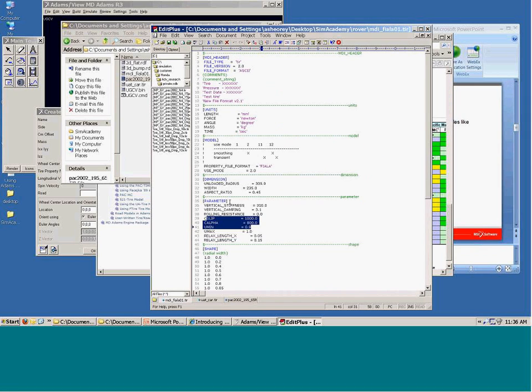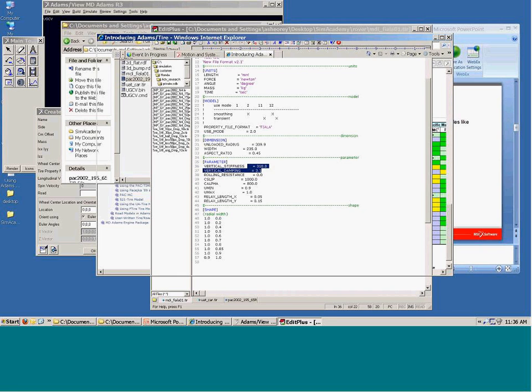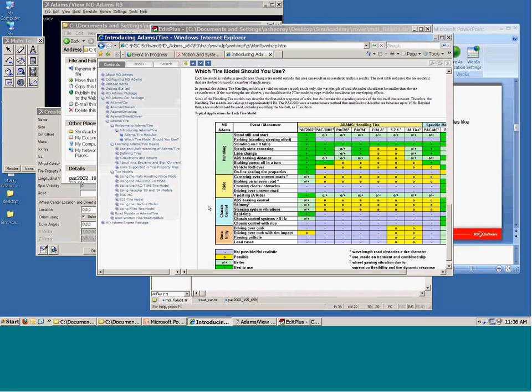So you have vertical stiffness, some percentage of damping. This is pretty obvious. And then you have some slip ratios and side slip. You can get good enough values, and then slowly move on to complicated ones depending on data availability.